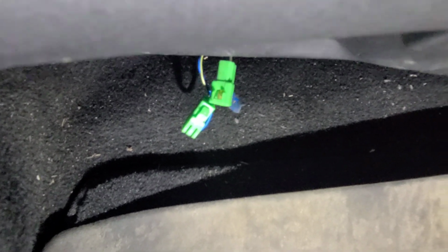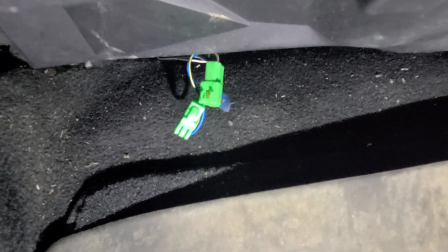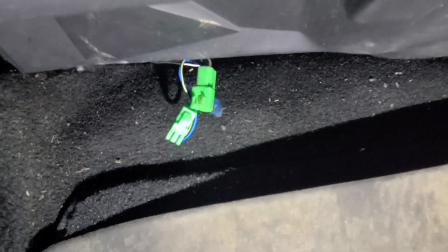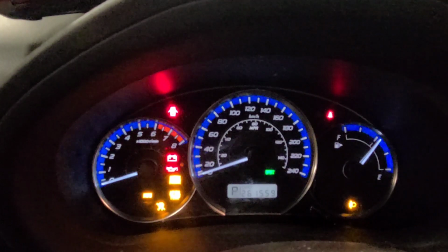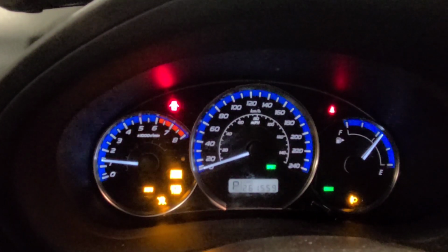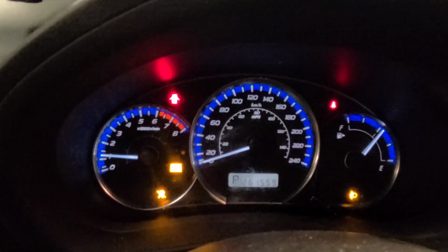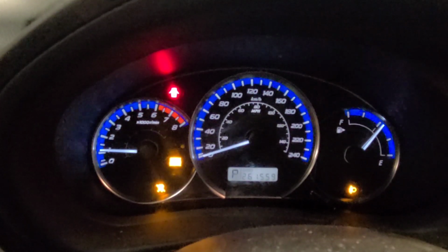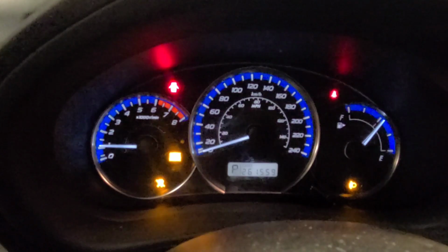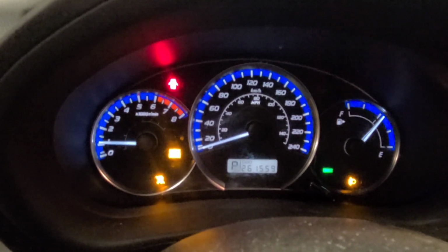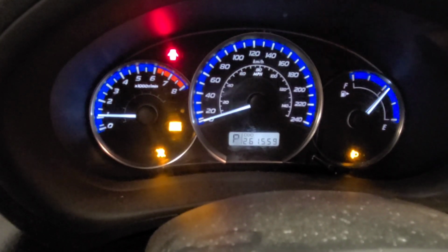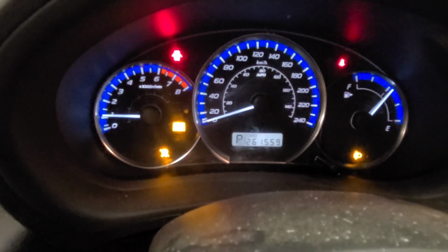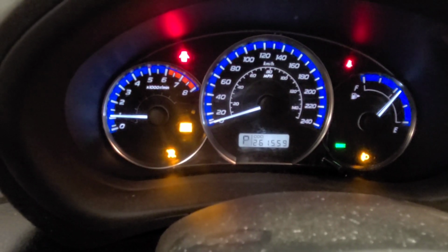Well, isn't that special? So I gather that's a self-test connector for some Subaru specific test, and it's not supposed to be connected. Let's see if that eliminates the flashing MIL. So I'm going to start it up. Check engine light is on solid now, and we likely have an O2 sensor heater code or something. Let's see if we can clear the codes, but that self-test connector is likely not supposed to be plugged together.